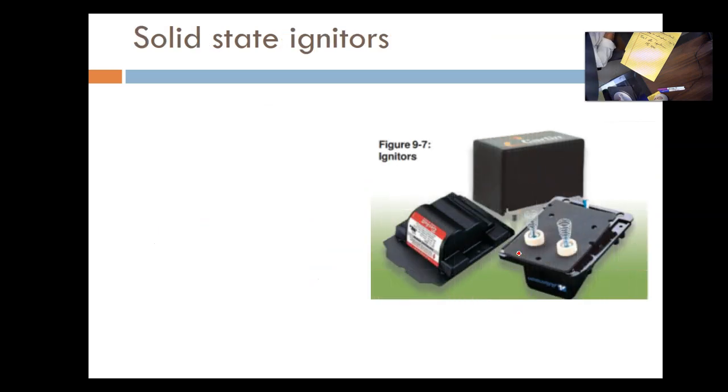Solid state igniters are really hard to test. They either work or they don't, so you just change them completely. There are a lot of tools that help you test them and make sure they have some power. Do not use the idea of getting the leads closer to each other and trying to bridge them. That might ruin your transformer.